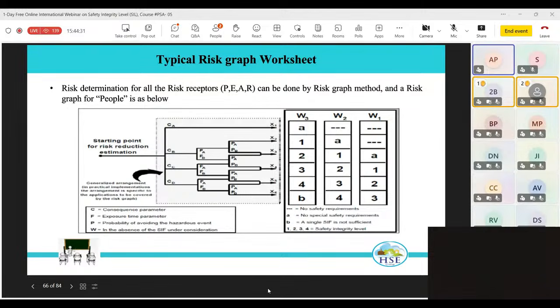While in the next thing we are going to study, LOPA, being a semi-quantitative method, you have a more resolute method of addressing this particular issue. Here, we are straightaway landing at SIL2 as the answer.